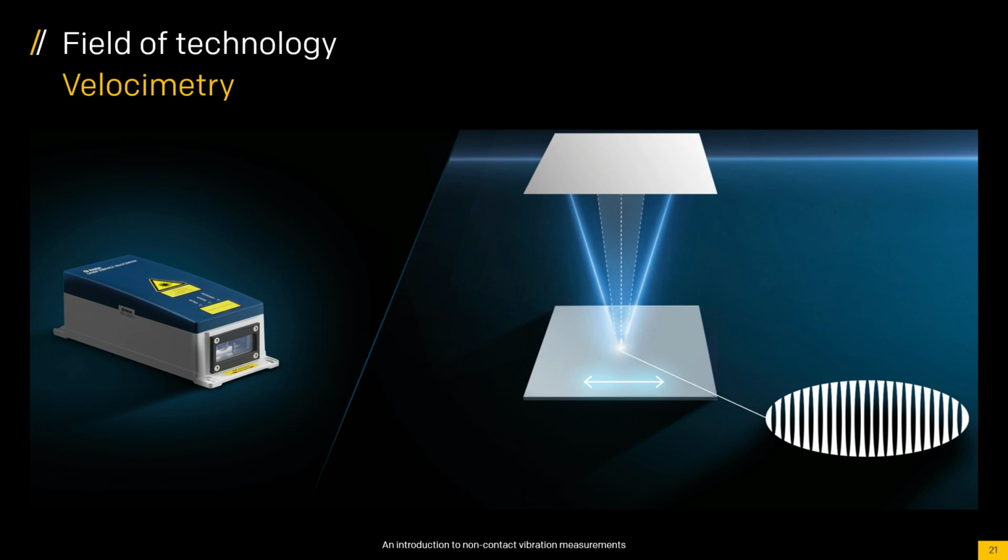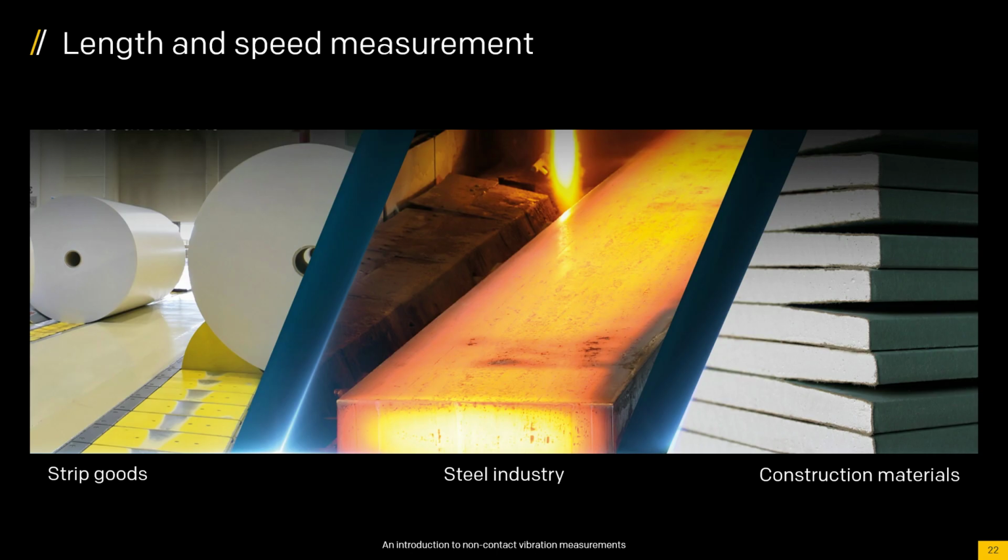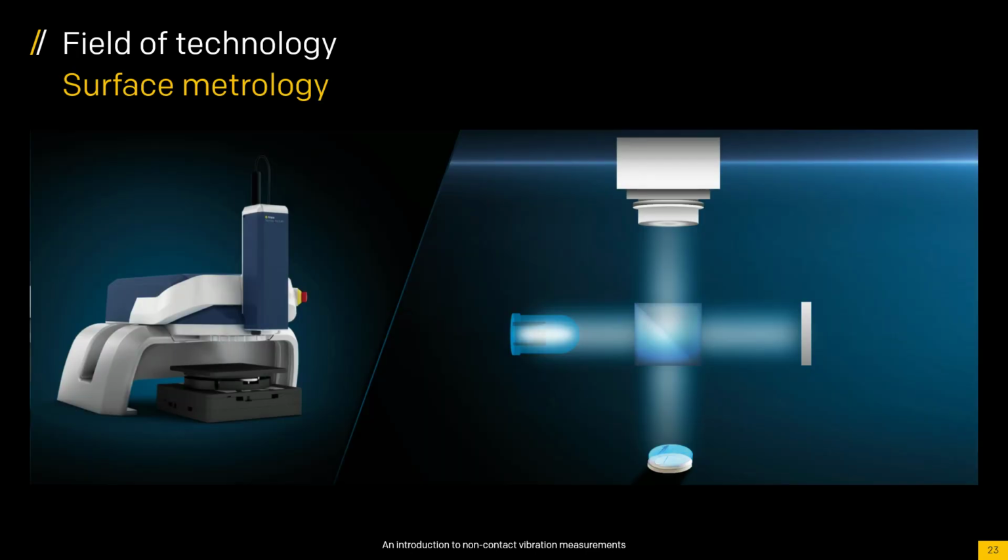Hmm. Sweep measurement, frankly, it's no different than a chirp or more broadband. There are two types of broadband excitations, I guess. Very broadly speaking, one is where you're putting all frequencies at once, like a periodic chirp or white noise or a burst random or a pseudo random. Or there is the sweep where you're going one frequency at a time, so you're putting all your energy in that one bin.